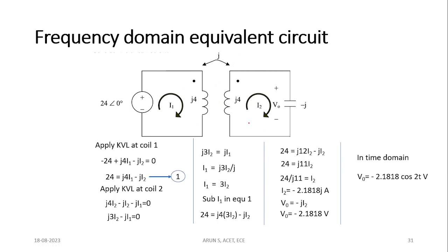So if I have this inductor and another inductor placed in close proximity, and current flowing through both inductors, there are two possible voltages you are going to get. One is the self-induced voltage, for which the polarity can be written based on the current direction. Another one is the mutually induced voltage. I'll change the color to blue for the mutually induced voltage.